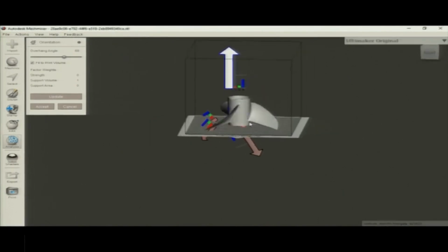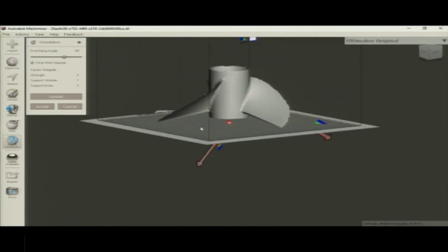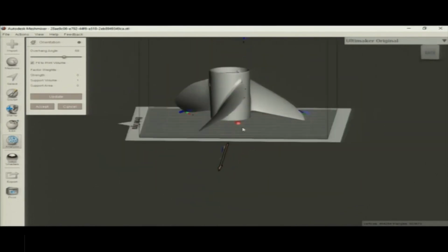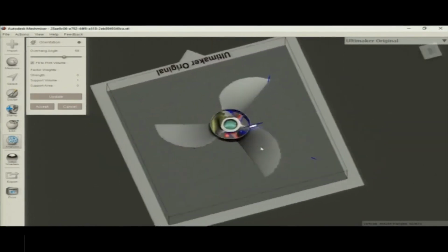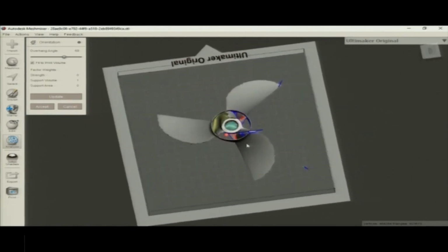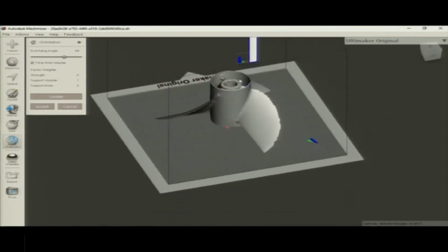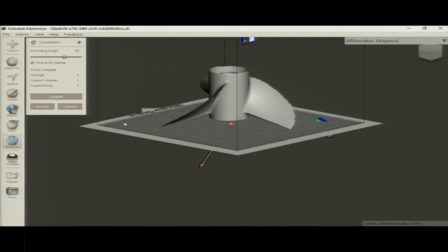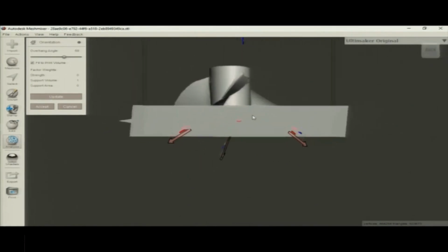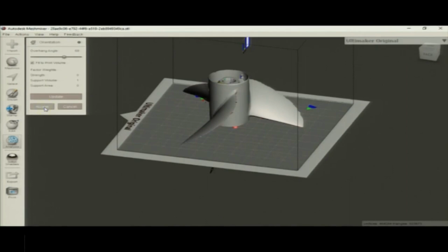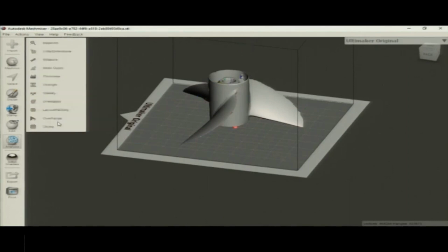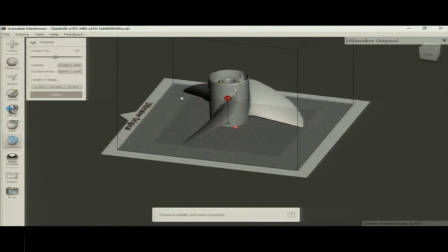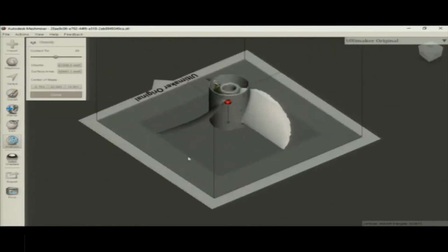So, now it is selected, and while putting it back in the volume, it has adjusted this orientation again. So, this is the orientation that is set by the system, fit to print volume. It is pretty symmetric in x and y directions, but if the model has unsymmetric geometries, this option will be greatly useful to have a successful print. Like for instance, the small model of animals or humans or some biomedical human ligaments or so.